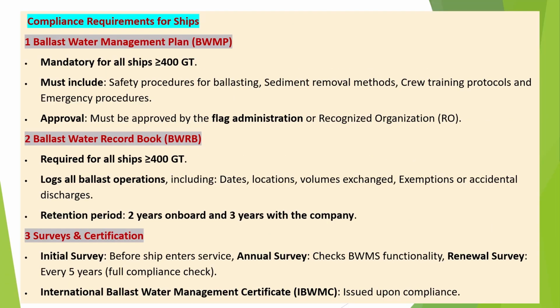Compliance requirements for ships. 1. Ballast Water Management Plan, BWMP. Mandatory for all ships greater than or equal to 400 GT. Must include safety procedures for ballasting, sediment removal methods, crew training protocols, and emergency procedures. Must be approved by the Flag Administration or recognized organization, RO.